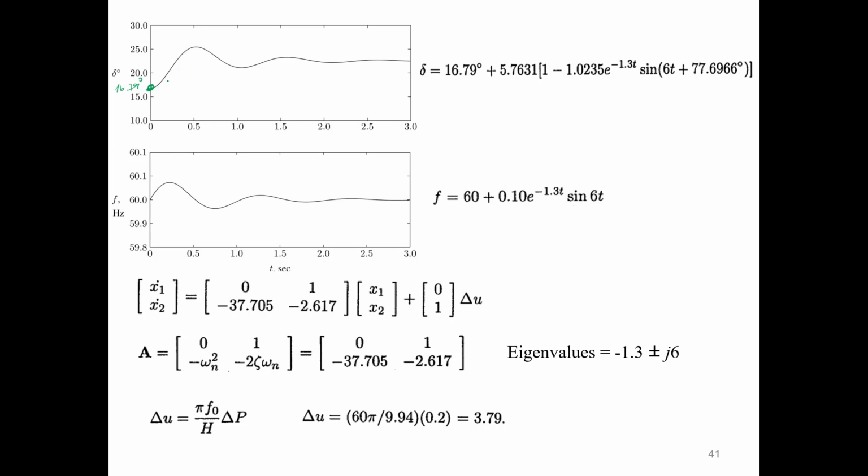When we change the power, there is a rotor excursion, a change in the rotor angle, and it reaches the final steady state, I mean the steady state at the new equilibrium point. This is the new equilibrium point after the load increase.